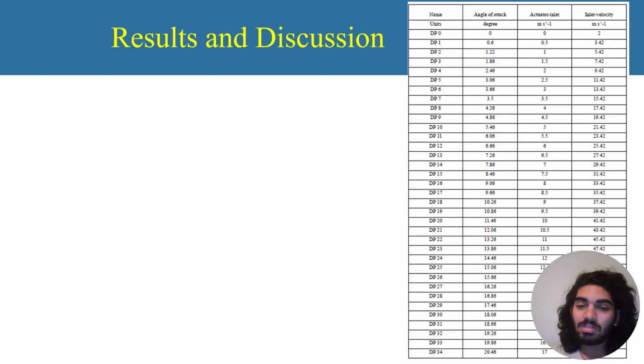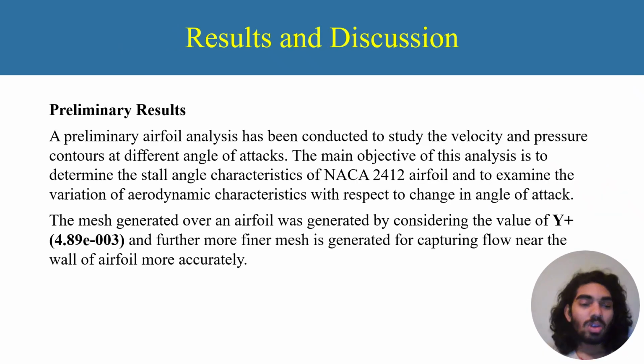So these are the results from the parametric analysis. I also explain how to do the parametric analysis in the video. In this, I considered the y plus value. Y plus is nothing but the height from the airfoil edge to the first boundary layer of the flow.